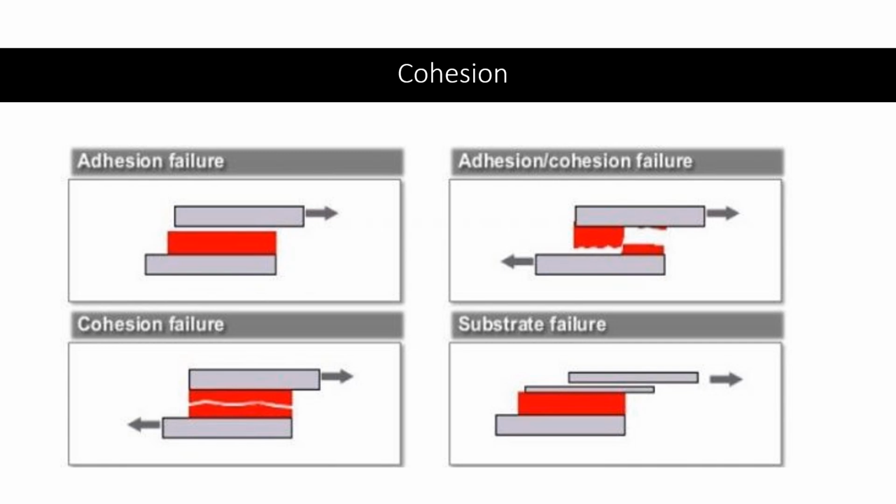That means that the bond was not strong enough to that specific substrate. Sometimes we get a mix of adhesion and cohesive failure, so we can also call that partial foam split when it comes to tapes, where you are getting that partial. This can be considered a success in specific circumstances.